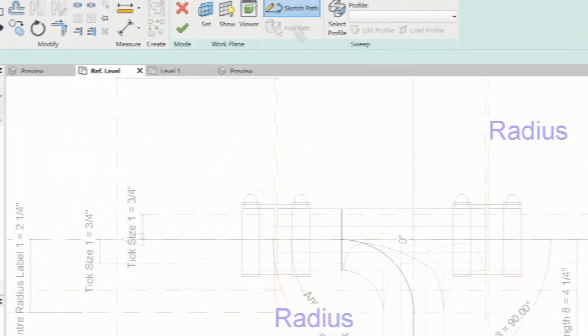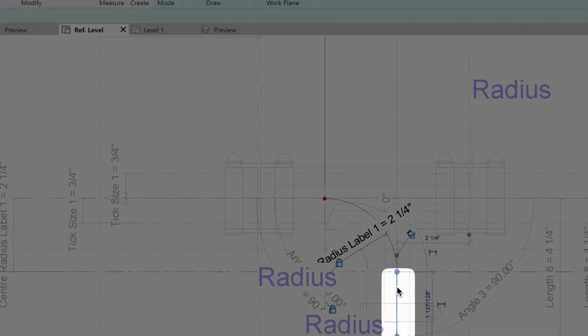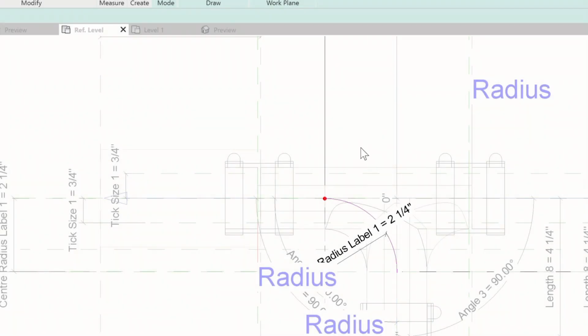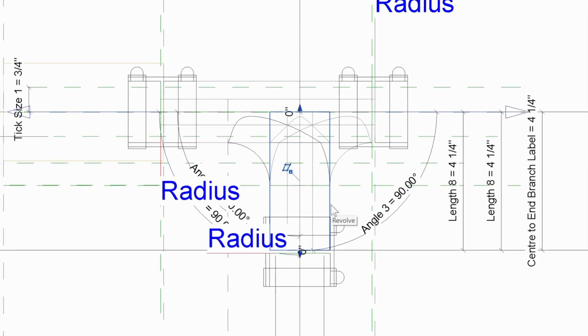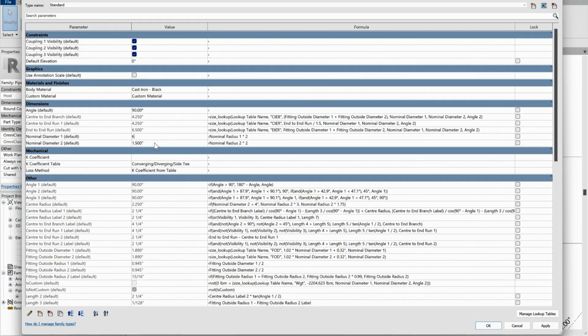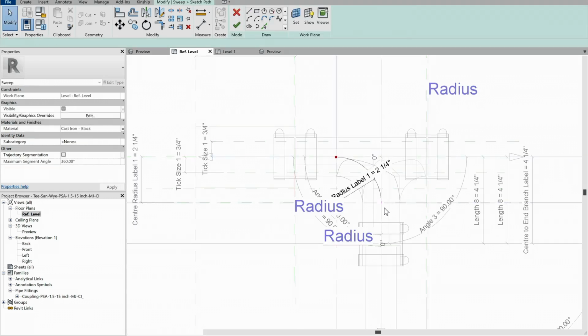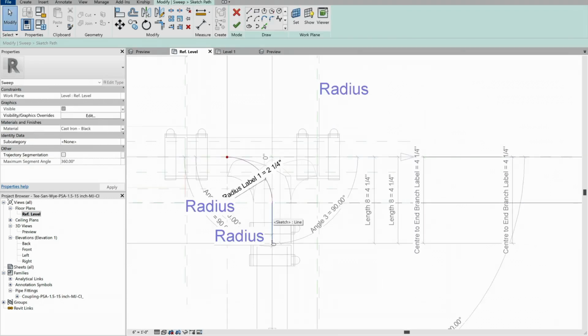Now we're going to quickly check into that other geometry, which was the 23482, and we're going to delete the branch line and then see if it still breaks. What we're doing here is deleting all the other geometry, so it's just that one in question. When we change the nominal diameters, it didn't flag up with an error. So now we know that the issue is the branch line is too small.